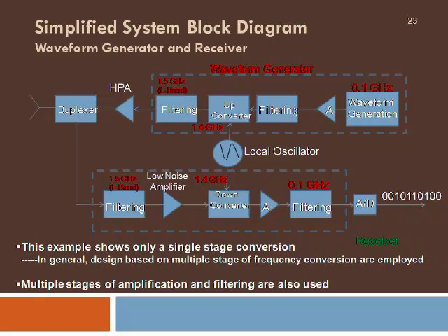The basic 1.4 GHz is generated by a local oscillator, and this additional 100 MHz signal is generated by a separate oscillator. So putting these two things together is what we got, this 1.5 GHz signal, which will be amplified to the required level using a high power amplifier. Then via a duplexer, it will be connected to the antenna.